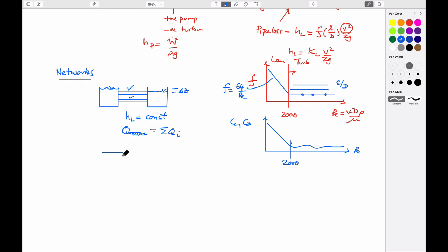And for flows which are segmented, in pipes of different diameters as they go upstream, from a pressure 1 here to a pressure 2 here, then the flow within each of these components, Q1, Q2, etc., has to be the same. And the head losses that result along this have to be the sum of the individual head losses on each of the individual components. And so physically, a parallel network versus a series network are different from each other, and we have to accommodate for that.